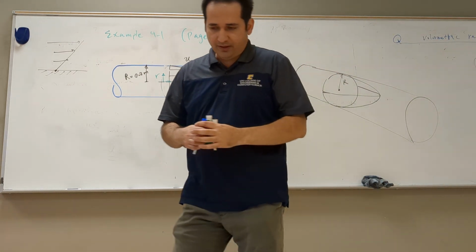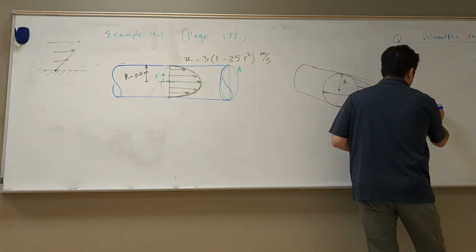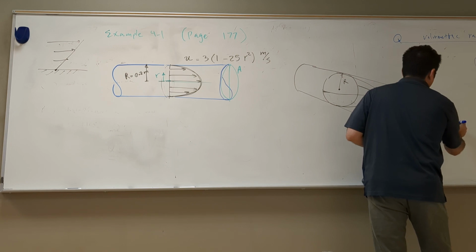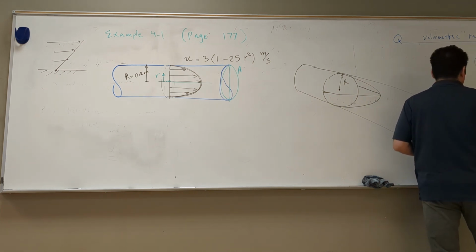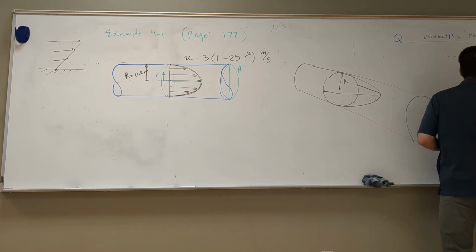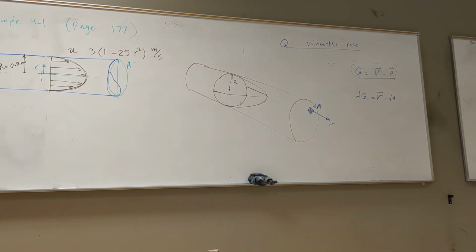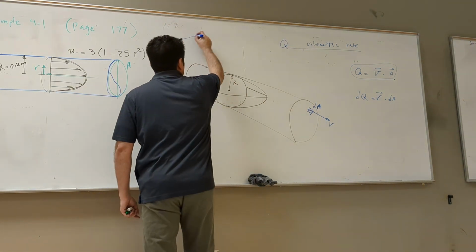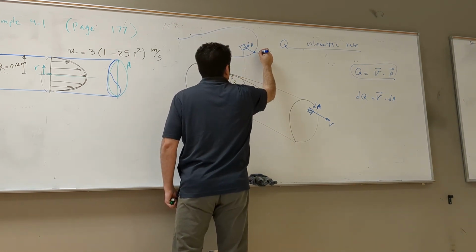But if it happens that you went through all those derivations, then you realize, oh, okay, this was considering just one element on a surface. The velocity here is say V, and this was dA. And in the finite version of this, you get V dot dA, dQ. That was what we had, and then we integrate that. So at every point, if you make an infinitesimal area, exactly like we did before. You remember I drew that potato? And everywhere we have a dA, and we have the velocity.